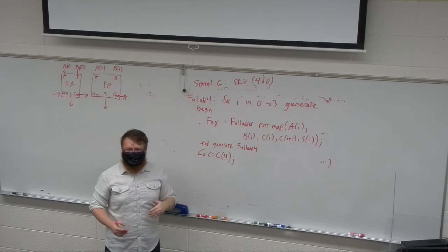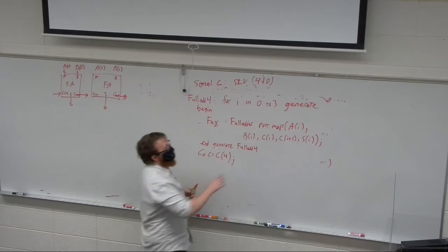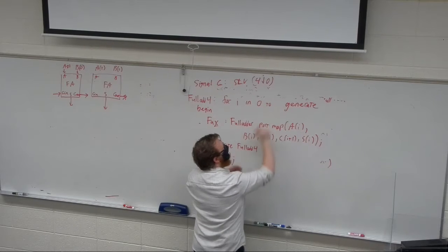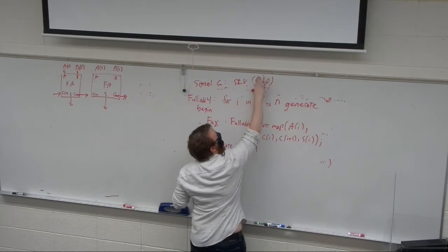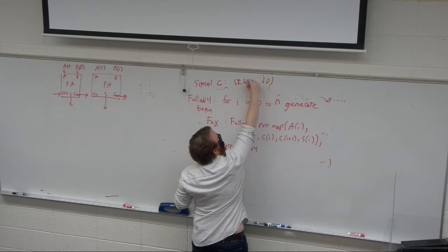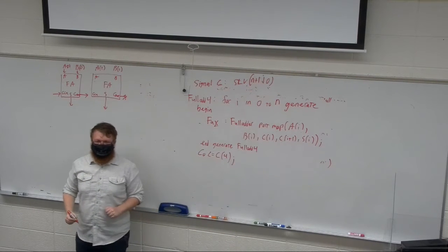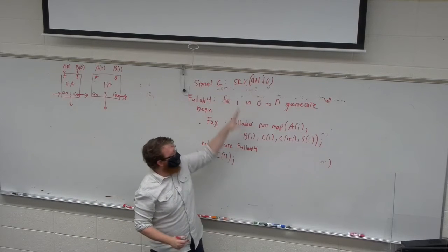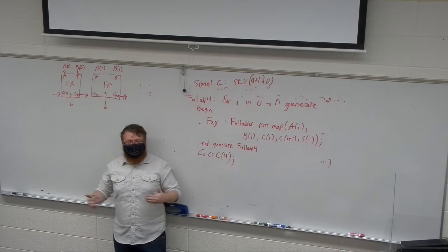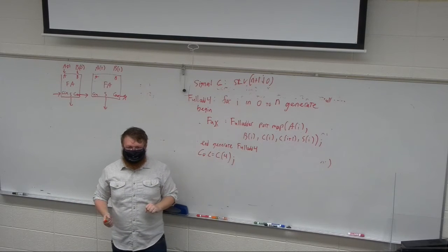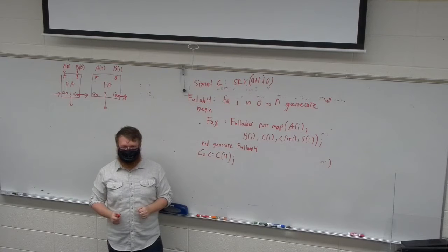Now, we could actually go back and combine this with the generic, and instead of using 3, let's pass it N. Now, we probably need to do a type conversion between that and that, but that's not really an issue, right? And so now we can generate N-bit adders with only a couple of lines of code.